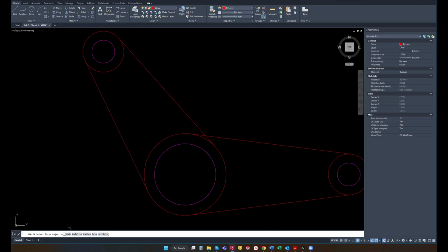And then down here, it's giving us the options: polyline, radius, trim. We're going to use the radius, so we're going to type R enter. And then it's asking us to specify the radius, so we're going to type 1 enter. Then it's going to ask us to select a first object and a second object. So I want to select somewhere in this area of this lower line that's tangent to our circle. And then we're going to select somewhere up above on this descending line right here. Click, and that will just trim off what we don't need on those two intersecting lines there.